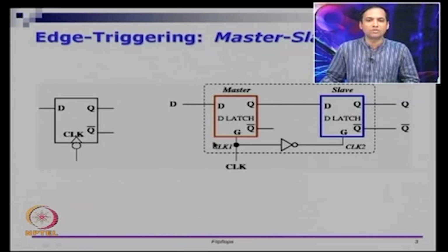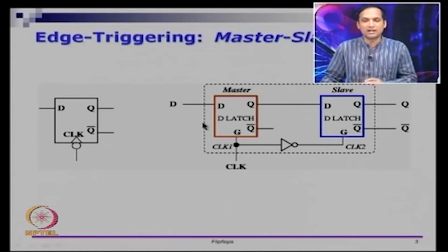The best way to think about that is to think of it as a black box first. It is taking two inputs, it is giving two outputs, and there are some interesting internal connections of the latches that we have done to get you the D flip flop. So, this is called a master slave D flip flop. Specifically, this circuit becomes what is called an edge triggered circuit. So, this circuit is not level triggered anymore.